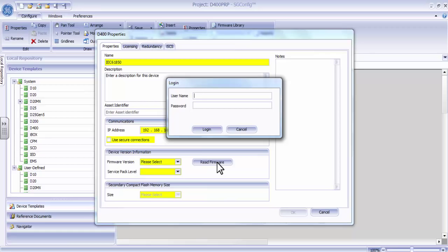So we log in with the HMI credentials, where supervisor is the username and the password is super123$, all small letters. Now when we try to log in, it should detect the firmware that's running on the compact flash cards.